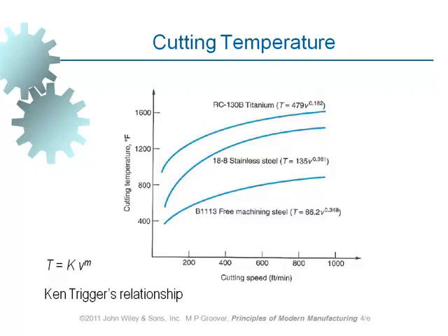And as you can see, as cutting speed increases, temperature of machining also increases. And it depends on the quality of the workpiece material. For each material, a different curve is given. However, the overall trend of the curves is similar: an increase in temperature as V increases.